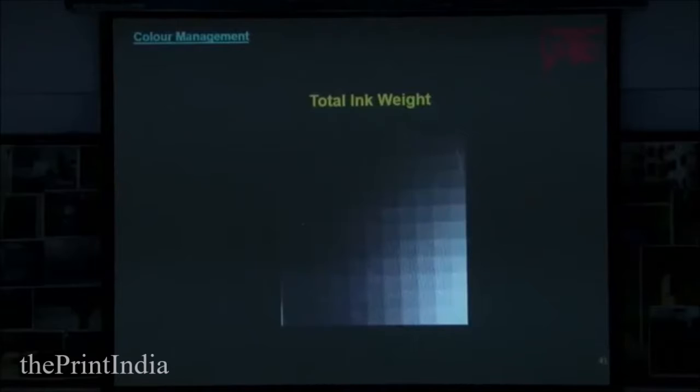Then when we print, and especially in the shadow, if you have good depth in the shadow, and if you print all the colors, 100% cyan, 100% magenta, 100% yellow, 100% black, the area becomes very heavy, and because of the ink trapping problem on the machine, the second, third, fourth color may not sit properly in that combination.